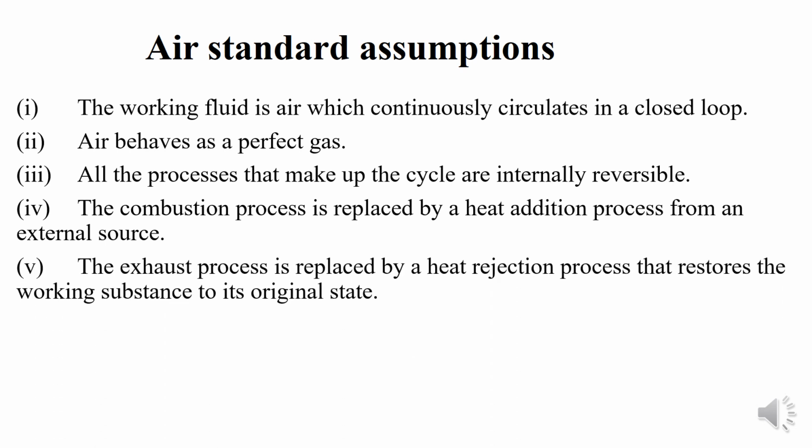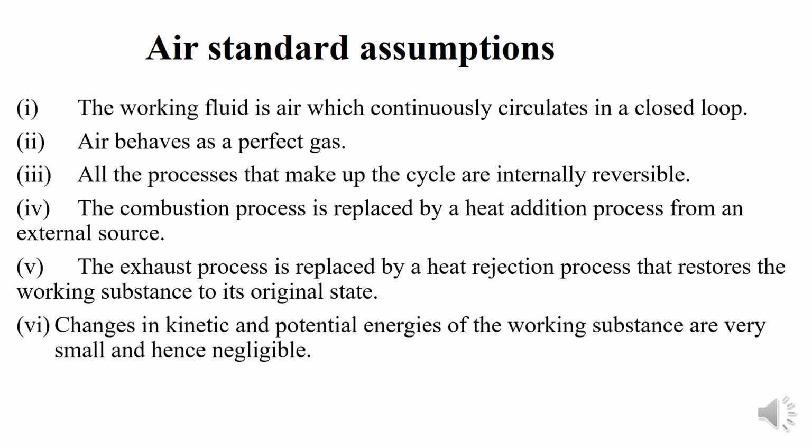The exhaust process is replaced by the heat rejection process, which is exactly the reverse of the combustion heat addition process. Similarly, a condenser is used where heat is rejected to the surroundings, so that the working fluid is brought back to the initial conditions.